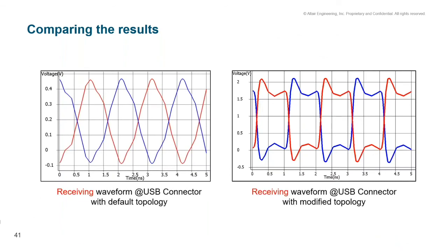And as we see in the video, it is very easy to adjust basically the network topology. And now here we'll see how the modified topology has a closer representation to the input square wave than that of the original topology. Well, there is a ripple effect after each transition though, which can be taken care of by adding filtering capacitors. In this way, we saw how easy it is to modify the topology to see what effect it would have on the waveforms. Various modifications can be done to the topology within a snap of a finger, and then the topology which outputs the desired result can be captured.